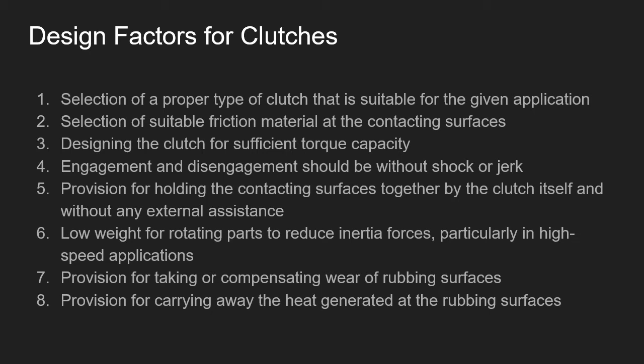Okay, the amount of torque that needs to be transmitted is probably the most important factor to be taken into account, right? Then you have shock absorption and means of engagement, low weight, and compensating wear, right? And heat generation. All these are design factors involved in friction clutches.